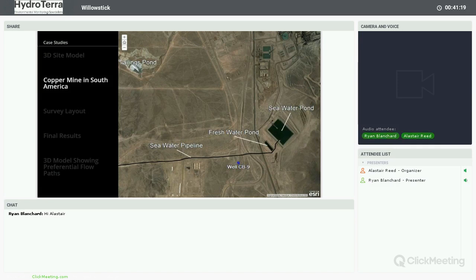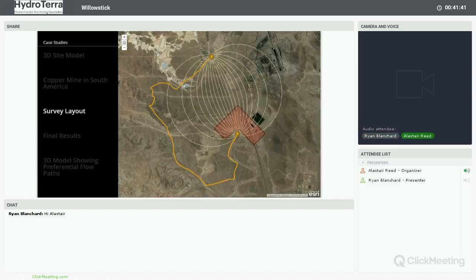And so they put together a remediation plan that was going to cost them about $6 million to reline and fix these storage ponds. And we came to them and said, before you do that, let us come out and do an investigation. We just want to confirm this is really the issue before you spend all that money. And so with that, we designed a survey you're seeing here with the upgradient electrode in the tailings pond, and then the other electrode we put in the well itself, and with our survey area surrounding the well, so we could get a really good understanding of what was happening.